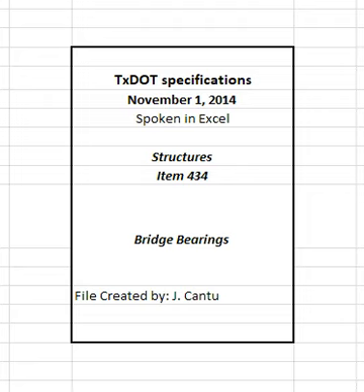3.3.1 Markings. Provide a permanent identification mark indicating each bearing's position in the structure and a direction arrow oriented in the forward station direction. Ensure the primary identification mark or a second such mark is provided at a visible location on the bearing after superstructure construction.